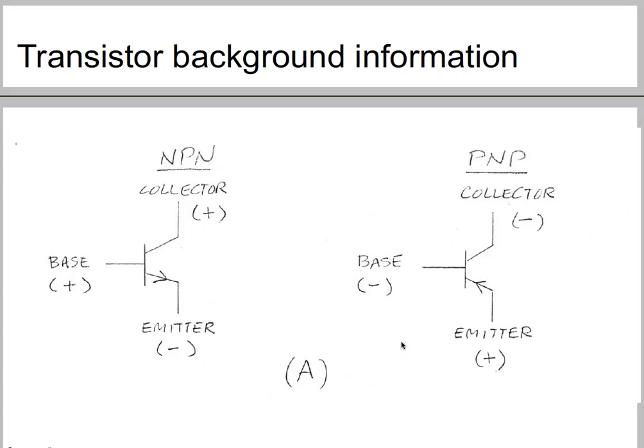You know that no single electronic component is as useful and as versatile as our transistors, and there are two basic types of transistors, the field effect transistor and the bipolar junction transistor. In a field effect transistor, they are operated by controlling the depth of a conduction channel between the source and the drain by varying the charge on the transistor gate, whereas in a bipolar transistor they are operated by controlling the current from emitter to collector by the magnitude of a small current through the transistor base.